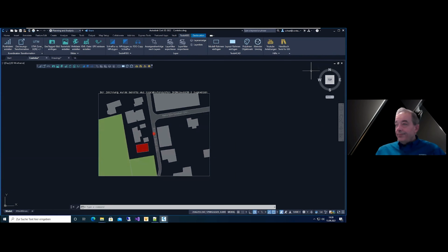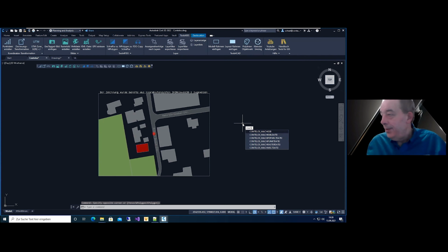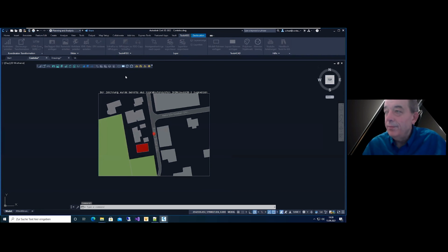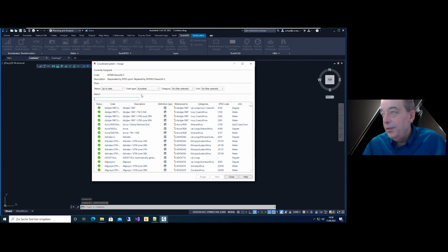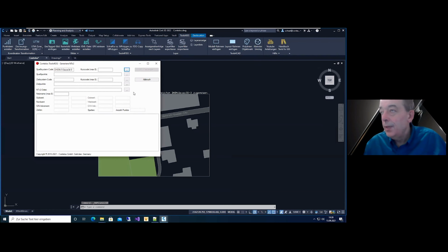When you have done this, you need a new command we integrated in our tool. Sorry, it's at this moment in German. We will translate it. First, you have to select the coordinate system of the source. For this, you use the normal coordinate library integrated in Civil 3D. And a short code for it.